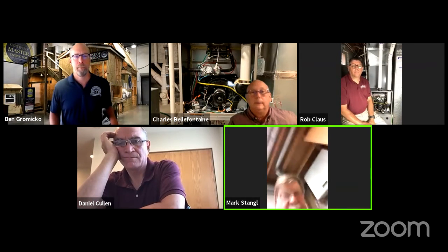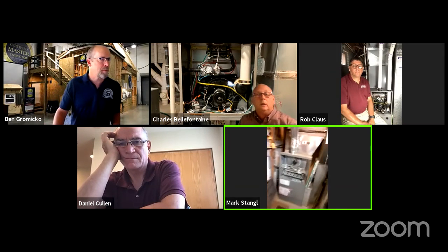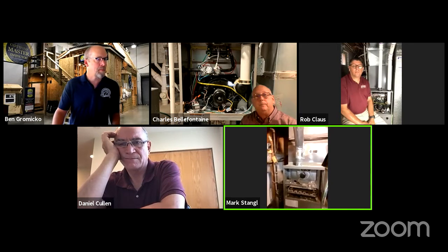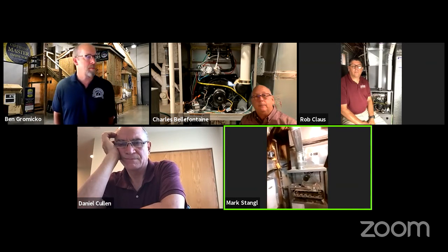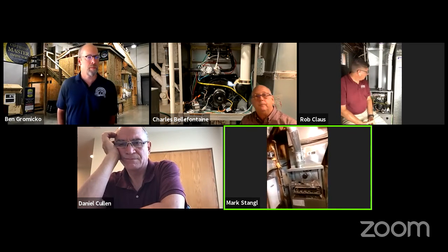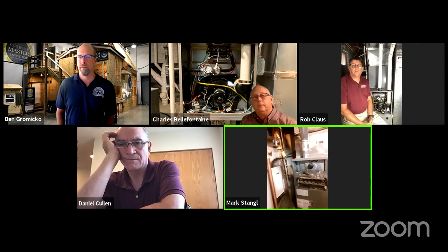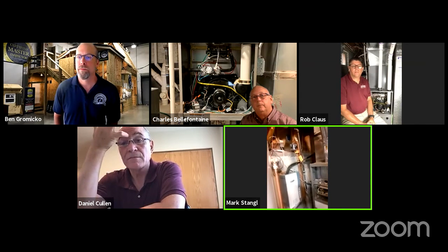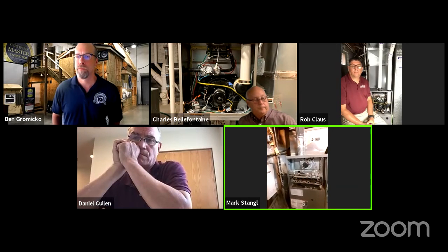Well, this is my simpler system. It's an 80% efficient forced air gas furnace, originally installed when I purchased this house 6 years ago. It has some common elements to Charles' system, and we've added a few other things to it. Initially, we have an inducer fan that comes on, and unlike Charles' system, we have a conventional chimney that goes from single vent to B vent all the way up to the roof through another story.